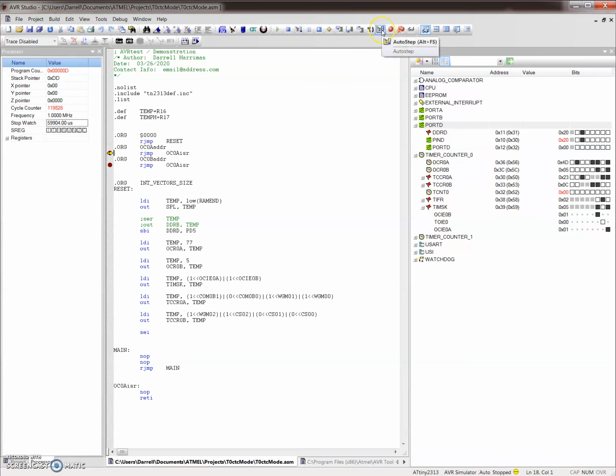Well, this is going to take a while. If I auto step, it's going to take way too long to simulate, because it takes 256 counts on our simulator to count once on the timer. So that's not going to work. We'll be here all day waiting for that. But we can see it's turning on and off. And we checked with our stopwatch, and we saw the timing was pretty good. So I think we have a pretty good program here, except we have very low resolution.